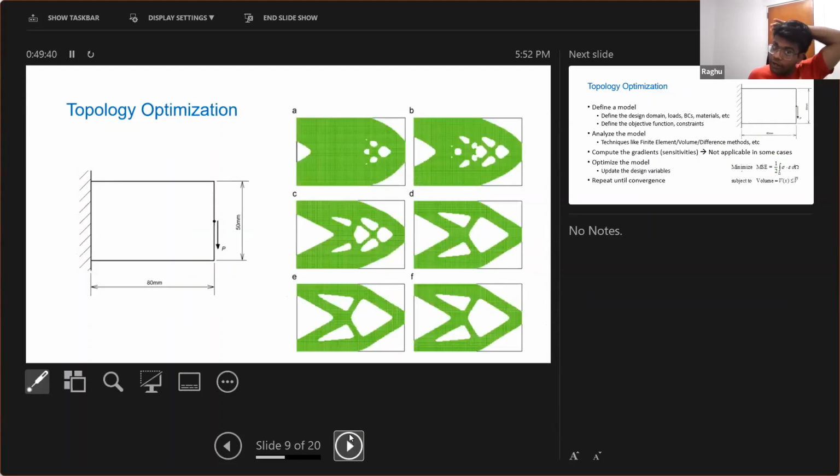So, in a very simple way, for topology optimization, a very simple algorithm: it's a 2-dimensional structure here. In civil engineering and mechanical engineering, it's called a cantilever beam. You might actually notice such a structure in your homes. If you have a TV hanging by the wall, the things which are connecting the TV to the wall are called cantilever supports. So this thing is the wall. This thing is a load, as in the TV example, this can be the load of the TV. So you want to optimize this cantilever structure, which is fixed to the wall when there is a load drawing this down, so that it has less weight.